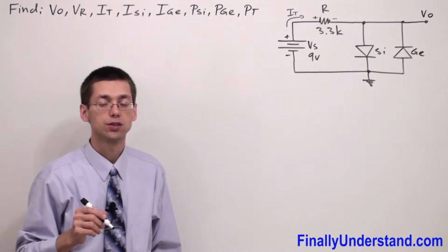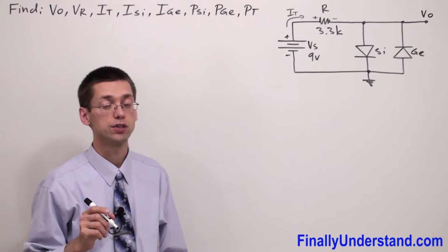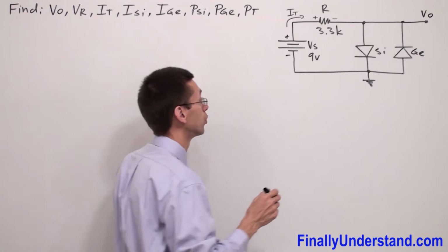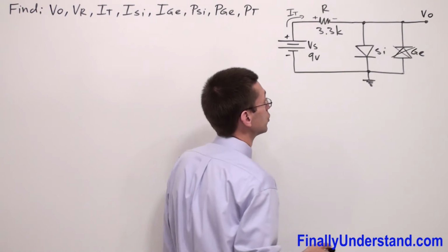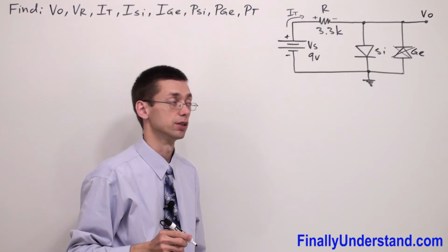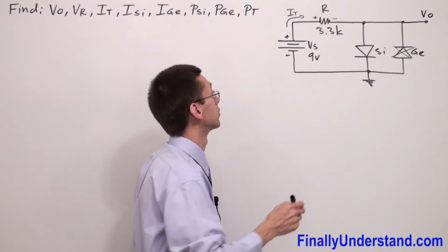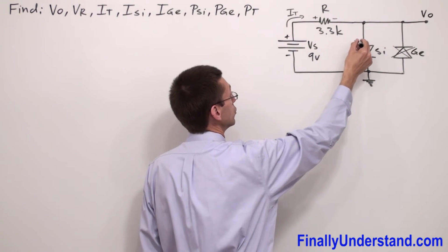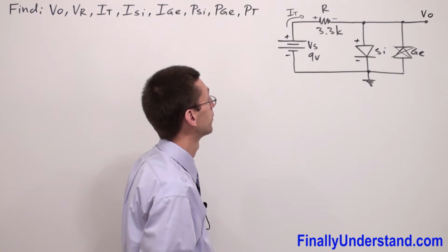So this diode is going to be in the off state. So this diode is not working. It's behaving like an open circuit, okay? So the current is not going to see this diode. So we have a simple series circuit, okay? Again, we have current going through the anode and leaving at the cathode. So I have a positive sign and a negative sign.